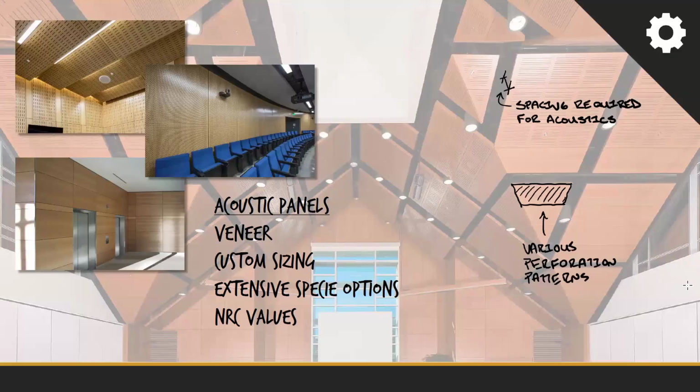With our acoustical panels, just like with our flat panels, we can go up to 4 foot by 10 foot and very, very high acoustical performance. You can get up to 0.85 NRC without insulation, and you can get up to 0.95 if you look at 1 inch or 2 inch of insulation. So again, when you work with your sales rep, let us know from the beginning what is your minimum NRC you're trying to achieve, and we can work backwards on what options we have available.